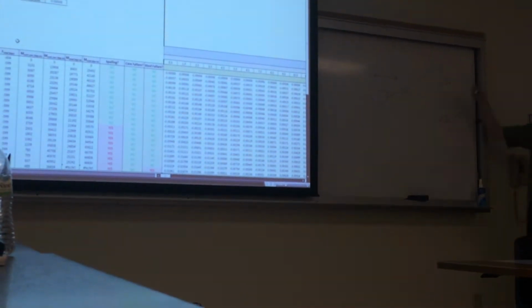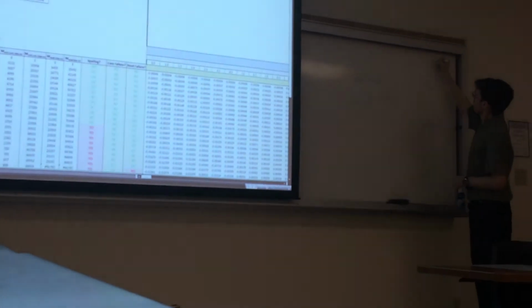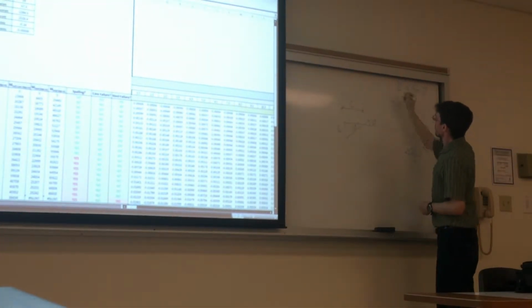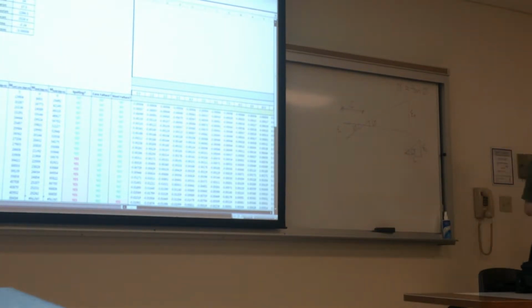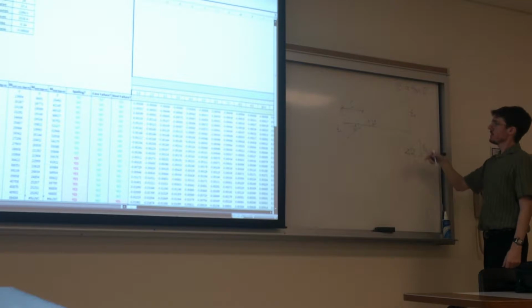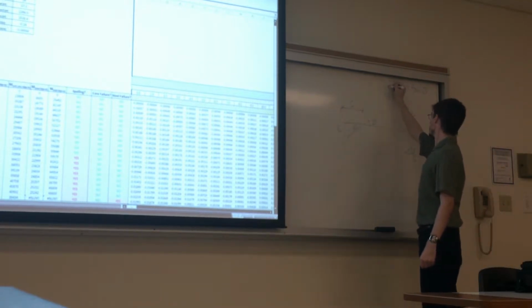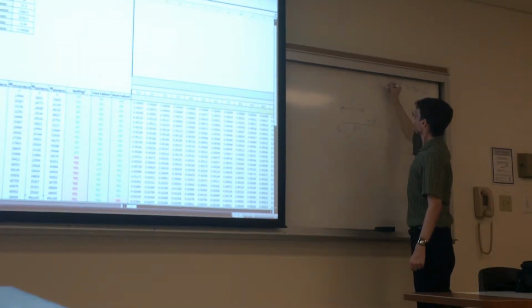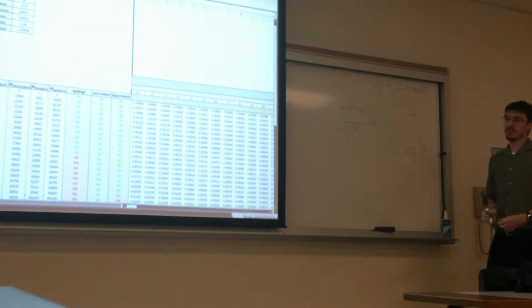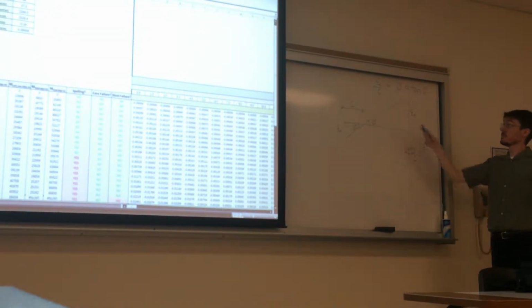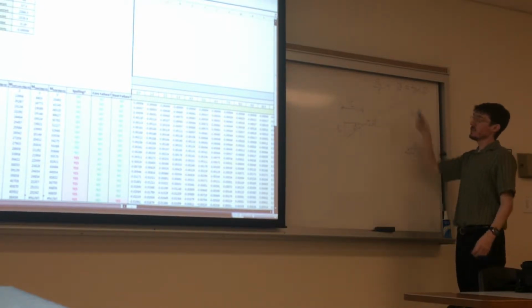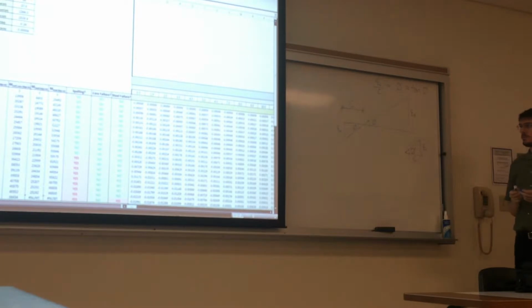You'd have this relationship for small angles where you say this angle is approximately equal to the tangent, and then you'd say this is equal to epsilon c over c. So you can easily rearrange this equation and solve for c once you have your initial guess of your depth of your compression region as well as your curvature increment.